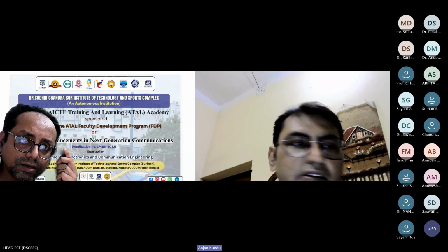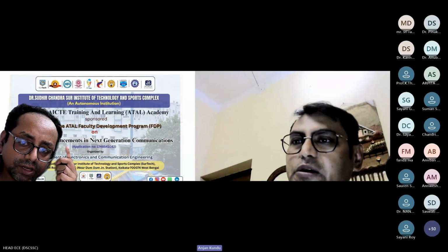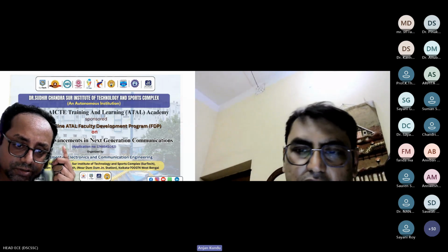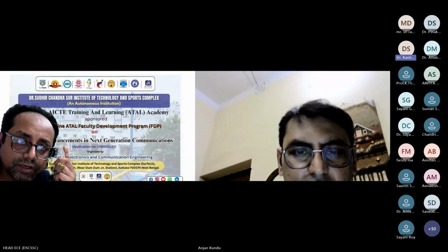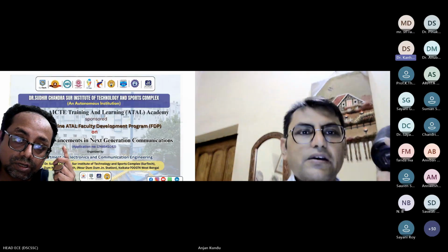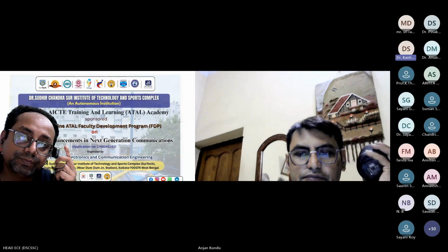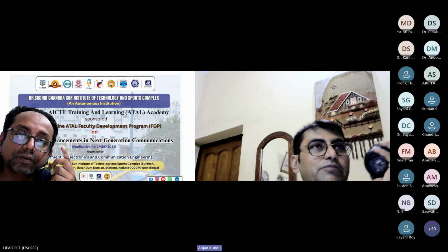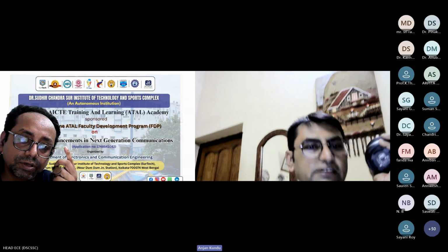I'm sharing a slide showing the position of the antennas, which I did during my PhD. Of course, that one is a theoretical study, but with minimum error I got that orientation. But in practice, sir, it will interfere with another signal, right? So do we need to design an absorber, or test only in an anechoic chamber? No, not in the anechoic chamber. Other than that, it can be done in a real-time environment, meaning in a noisy environment with minus 10 dB noise.